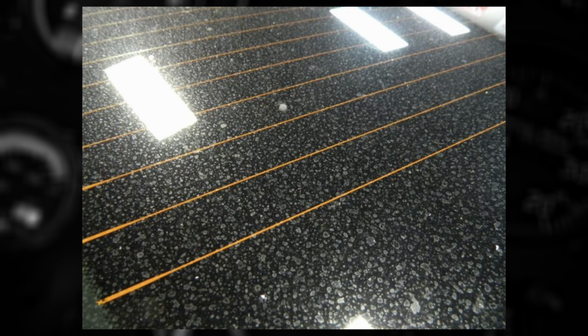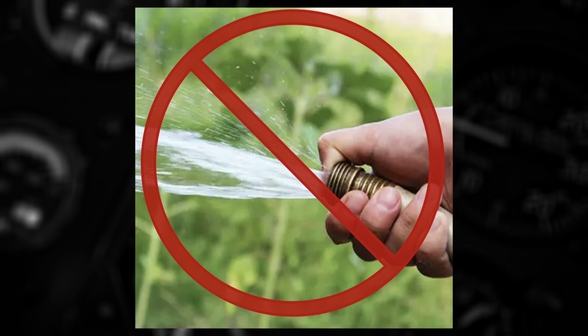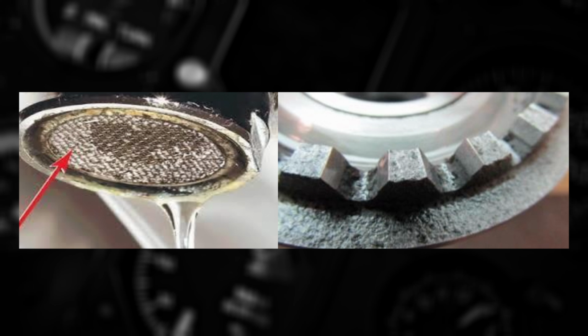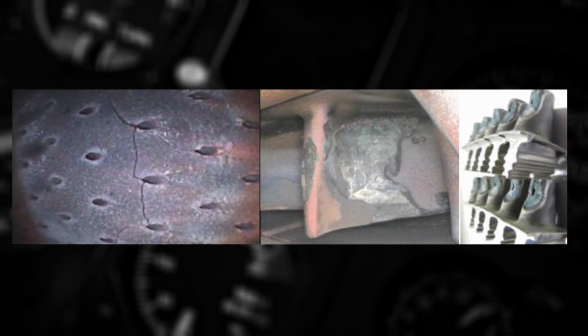All of these lead to a reduced performance and a significant increase in repair costs. You must use distilled or demineralized water meeting the specified standards. If neither are available, water meeting the minimum specified quality can be used, but only during the cranking procedure.